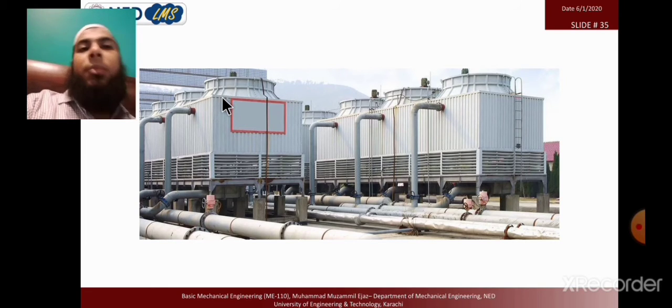And the second way is the evaporation process. Through evaporation some amount of water attaches with air and is taken away with the air, so the remaining water left gets cooled down. So in the cooling tower we also have a makeup line, because some of the water is rejected into the atmospheric air. So the amount of water lost from the condenser water is adjusted with the makeup water, but due to this evaporation a lot of heat is rejected from the condenser water.